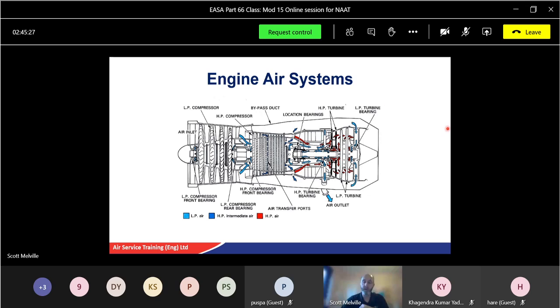So we can control the amount of cooling air, etc. Because remember, the air from around here can be about 500, 600 degrees, maybe 550 thereabouts. So again, we can tap that for the turbines, that's fine, but also it's already hot before it's going to the combustion chamber. If some of that hot air escapes, then potentially that can cause a fire hazard in the cooler area of the actual engine.